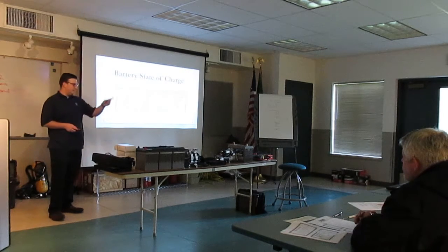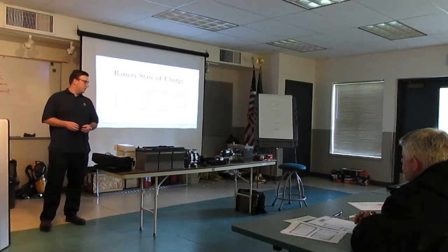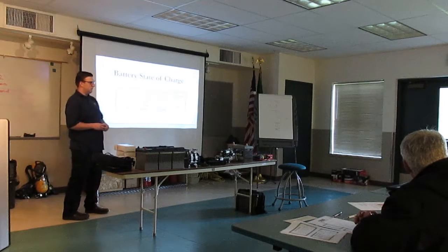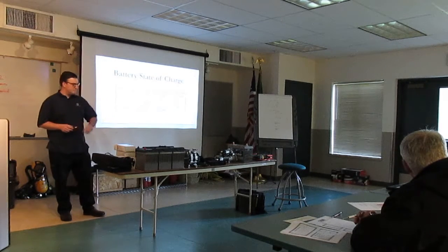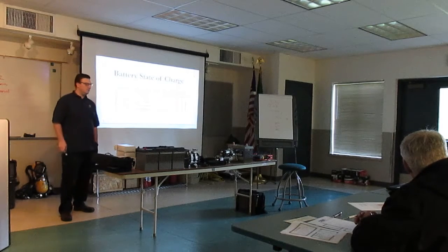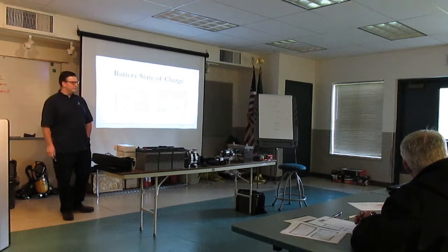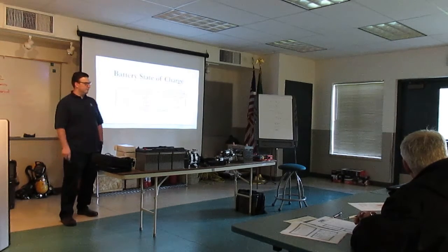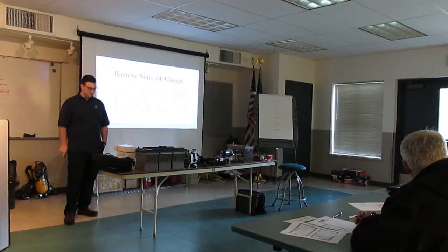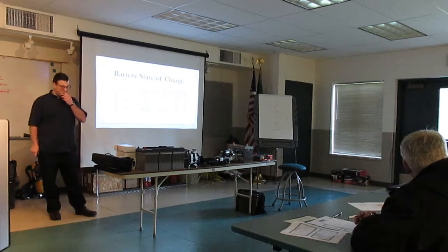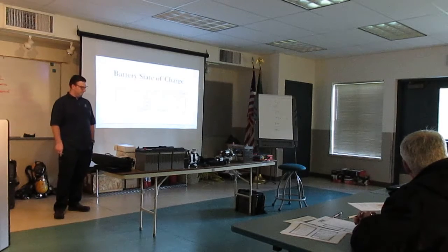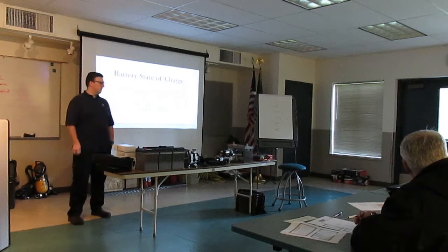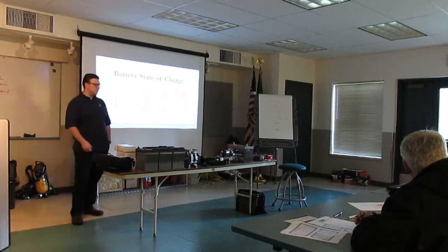So we did a build in FDNY where they built 70 trucks with 400 amp alternators. They were cooking alternators about 6 months in. We went there to find out that the alternators were severely overloaded. Whoever did the build, I'm not going to throw them under the proverbial fire truck, but when they did the load calculations, they did not include battery loads. It was way off. I think the alternator at idle was 60 amps under what was needed.